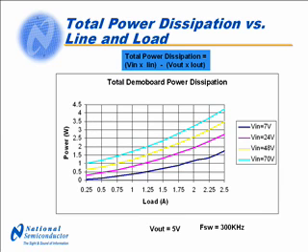Shown on this slide is the first step in determining the regulator junction temperature. This data was taken from the efficiency graphs that we looked at earlier. Instead of calculating P out divided by P in, we are subtracting P out from P in. The difference in power is the total power dissipated in the conversion process, which has to be dissipated on the board itself.